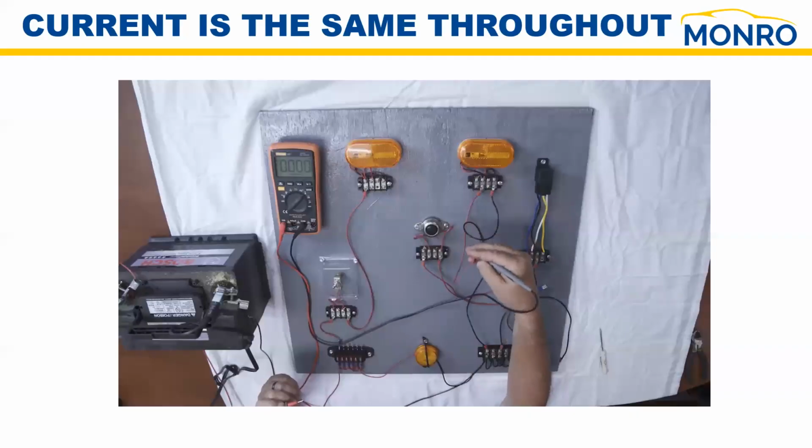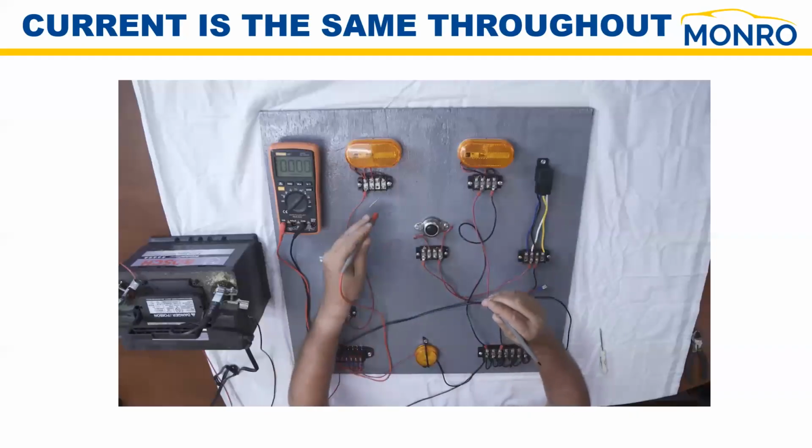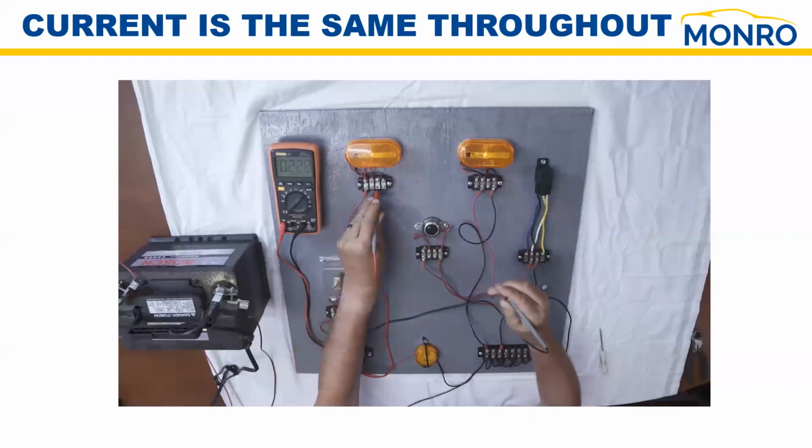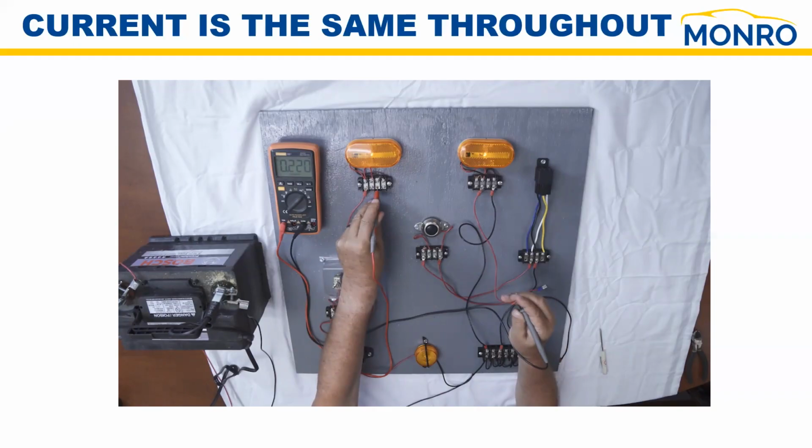Our digital voltmeter is already placed on the amp scale, just like we did when we covered this in basic amps. We know we're measuring current because the meter became basically a jumper wire. And at that point, we were looking at approximately 0.220 amps.